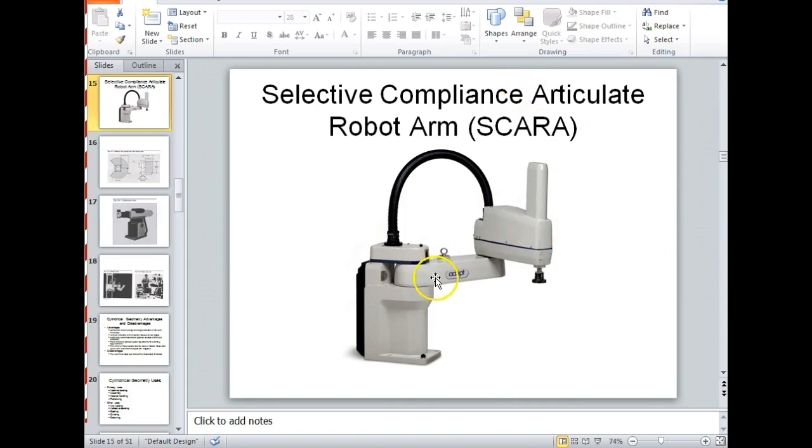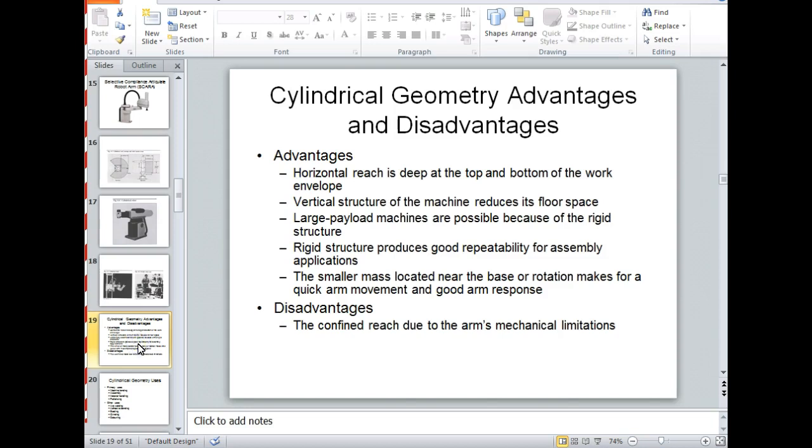And of course, the advantage of the SCARA robot is very simple. It usually has a 2R, but they're horizontal. And then we got at least 1 P. It might be a 3R. A lot of times what they do is they give the ability to rotate it. You can't do roll, pitch, yaw with these guys. That's why they're very popular with pick and place and assembly. So sometimes there'll be a 3R, sometimes there'll be a 3RP, or a P3R. That may be the difference.